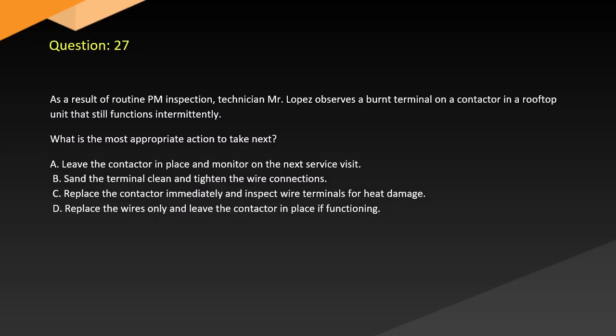A. Leave the contactor in place and monitor on the next service visit. B. Sand the terminal clean and tighten the wire connections. C. Replace the contactor immediately and inspect wire terminals for heat damage. D. Replace the wires only and leave the contactor in place if functioning.